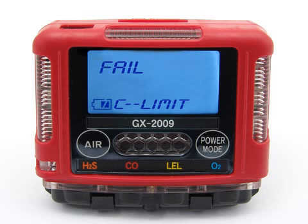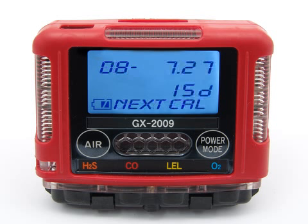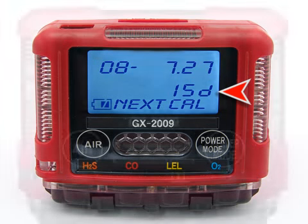If the unit is due for calibration and the Cal Limit check is set to Can't Use, then the Fail Cal Limit prompt is displayed. At the same time, the alarm LEDs and buzzer will pulse several times. The Fail Cal Limit prompt will remain on the display until the unit is turned off. The GX-2009 cannot be used until a complete calibration has been performed. If calibration is not due, or the Cal Limit check is set to None, then the display will indicate when the next calibration is due.